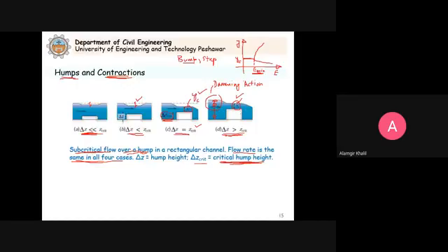This we will discuss in detail. It says that now you see here, because of damming action, we have this YC. We will solve a problem on this. They say that the depth here must be supercritical, and then there will be a hydraulic jump, and then it will establish the normal depth, and the water will continue. So the depth immediately downstream must be the supercritical depth. It cannot be the subcritical depth. We will solve a problem on this, to see what the reason is.